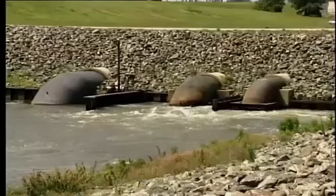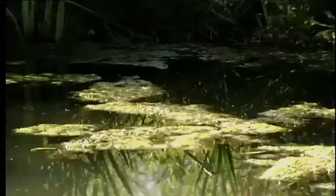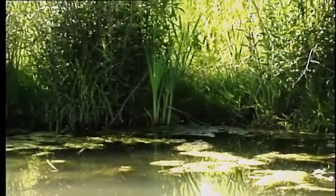So what are the effluent contaminants that cause environmental problems? One obvious item is the value of pH. This should normally be within the range of 6 to 9. However, more important is the need to maintain a steady pH value in the river or lake. Even small changes may have a profound impact on the ecology, that is, the plant and fish life.